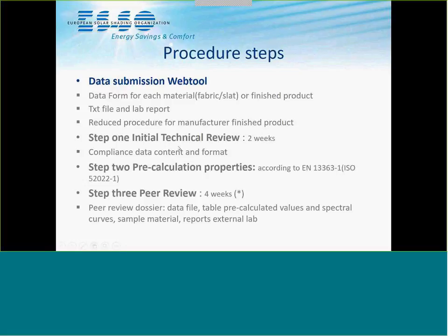So we have an initial check which counts for 2 weeks to see the data are compliant and the format is correct. The tool will then pre-calculate the properties according to the simplified method of the EN 13363 standard, which is also becoming an ISO standard.